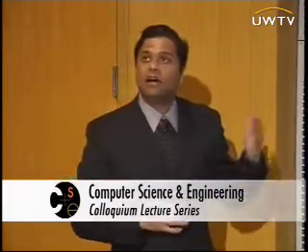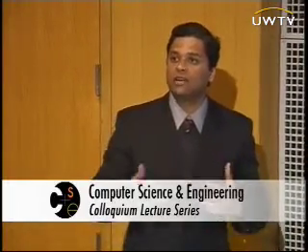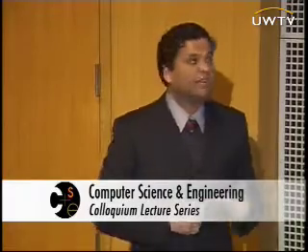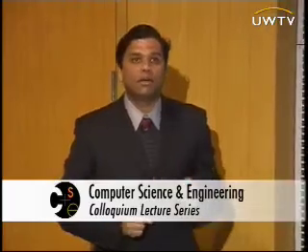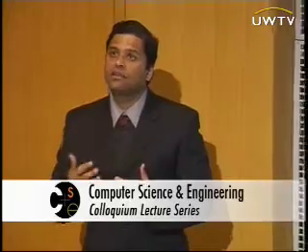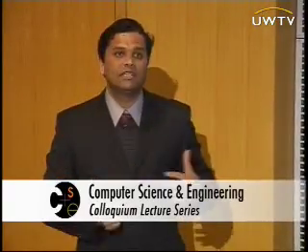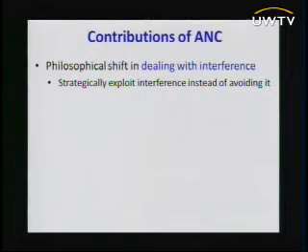Now, as you can guess, I'm hiding a lot of details under the rug here. There's a lot of engineering to be done to subtract these signals correctly. But before I get into those details, let me talk about the main contributions of analog network coding. First, analog network coding advocates a philosophical shift in the way we deal with interference. Traditionally, wireless mesh networks have used very conservative scheduling protocols to avoid interference at all costs. Instead, we show that we can strategically exploit interference to actually increase network throughput.